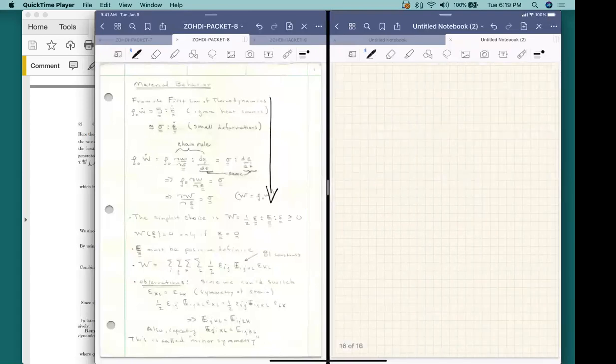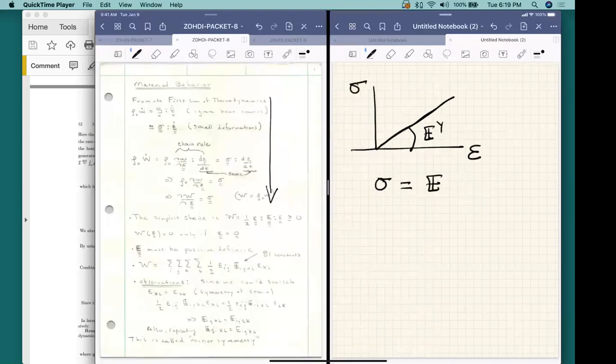As an example, Hooke's law, of course, we know and love it in 1D. It says that stress and strain are related by this parameter, the so-called Young's modulus. And the Young's modulus simply says you take this funky factor that's the stiffness of the material, you multiply it by the strain, and you get the stress-strain relationship, the very beginning of everything.